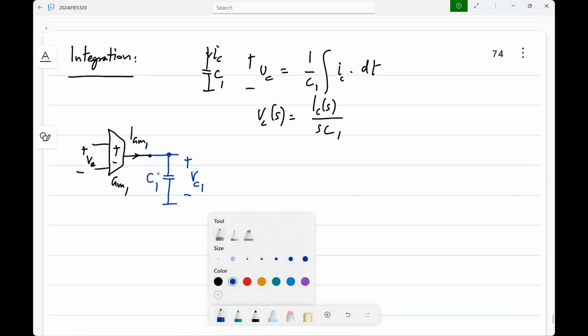Now what is the problem? We have the parasitic element RO1. Whatever the voltage across the capacitor is, that is also appearing across RO1. That is the problem. So we can think of this as a problem of making a better current controlled voltage source. GM is providing the current, and if you pass that through some impedance, you will get a proportional voltage: that current times the impedance. Now the point is that the same voltage also appears across the output conductance of GM1 itself.